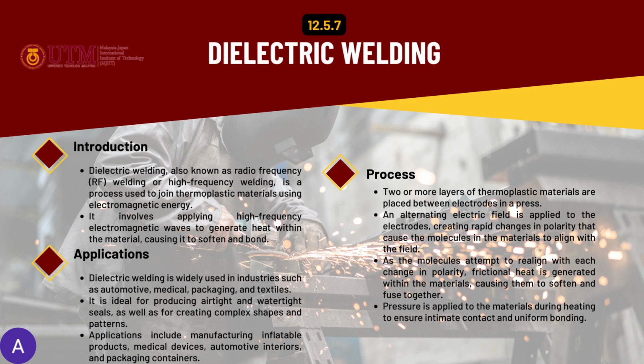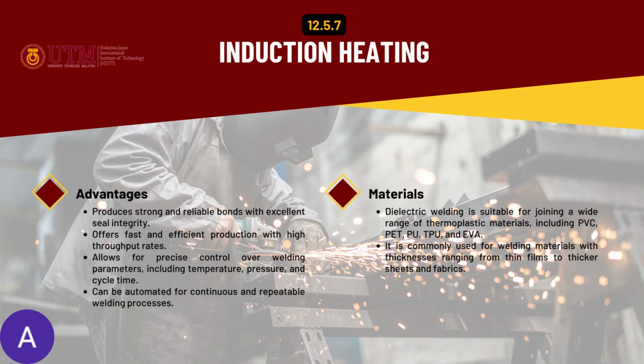So, common applications for dielectric welding are in industries such as automotive, medical, packaging, and textile. It is ideal for producing airtight and watertight seals as well as for creating complex shapes and patterns. Advantages are that it produces strong and reliable bonds with excellent seal integrity, offers fast and efficient production, allows for precise control, and can be automated for continuous and repeatable welding processes.